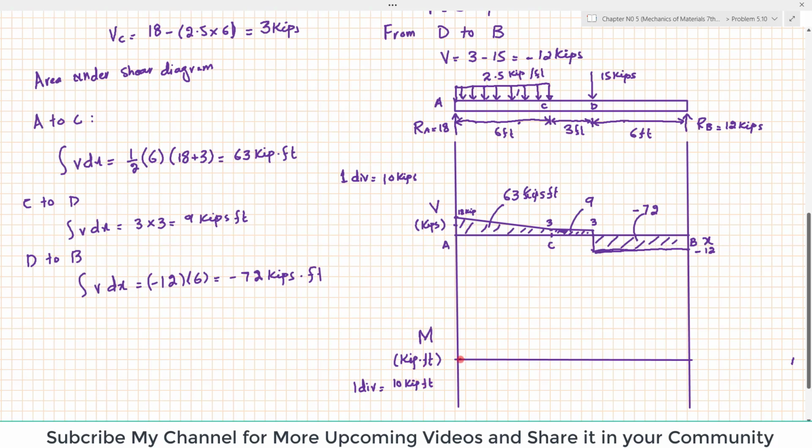So at point A, we have bending moment MA, which is equal to 0 because this force is passing through point A. So bending moment at point A will be 0.